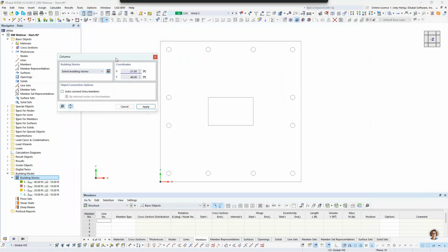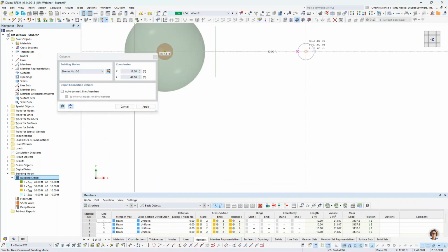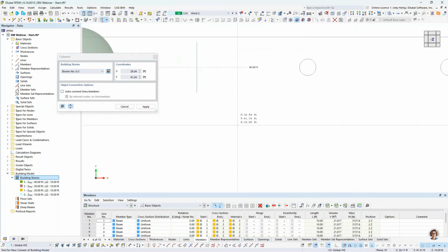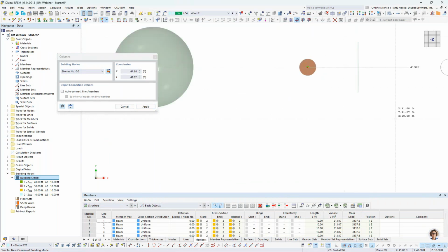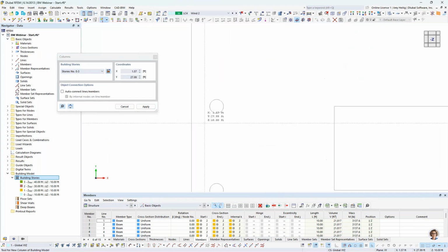But you'll notice a special dialog box here, again, specific to the building model tools, where I can draw this column, but apply it to all stories. So all stories are activated here. And now when I zoom in to my DXF drawing grid, we can go ahead and just apply these columns by a single click here at the center of the background layer.